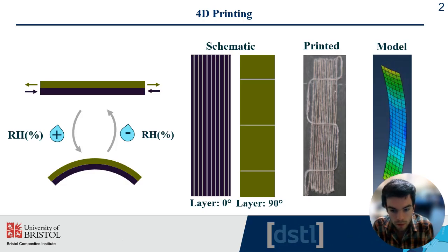So in this work we're going to talk about 4D printing, which is basically adding a fourth dimension to 3D printing. This fourth dimension is time. So basically in 4D printing we give enough time for 3D printed structures to transform, deform and actuate. In this presentation only bending is going to be considered, and only with humidity stimuli. This actuation is created by a bilayer actuation.